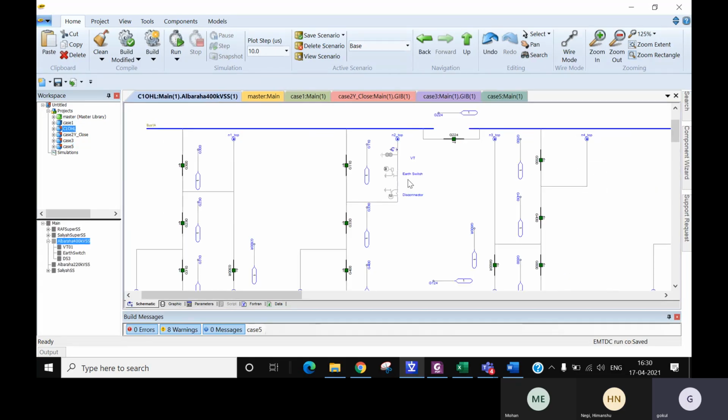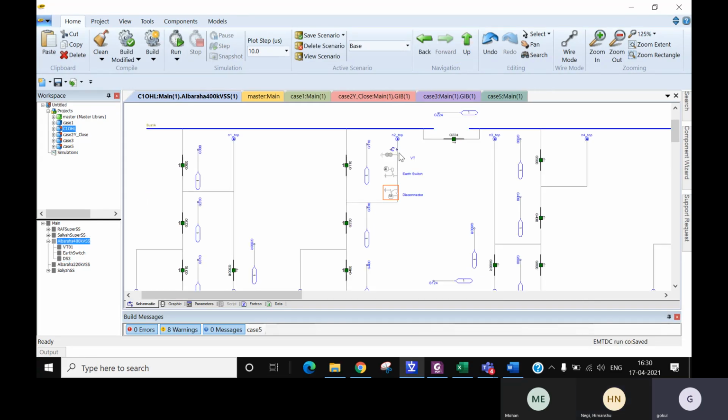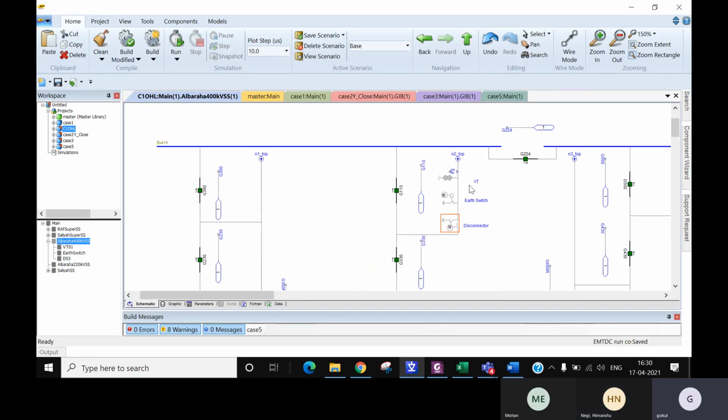And here, what I'm going to do is energize this VT, this line side VT. So this disconnector will be in the closed position, and I'm going to measure only between this. Here there will be no voltage, and here there will be no voltage. How are you energizing this VT then? From the top, N2? Yes, exactly. I'll show that.